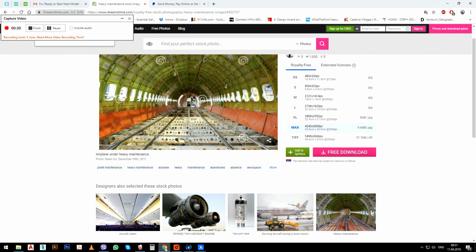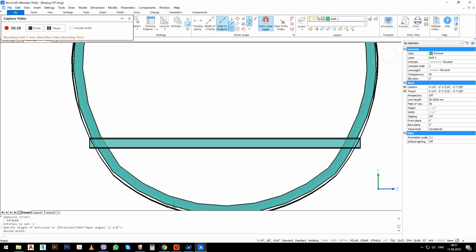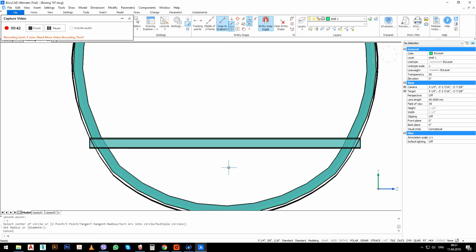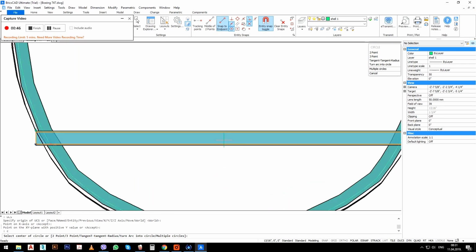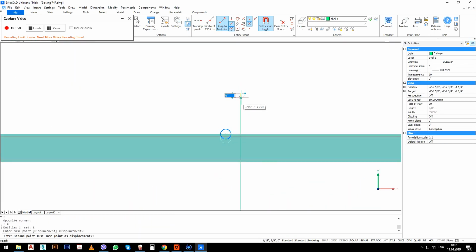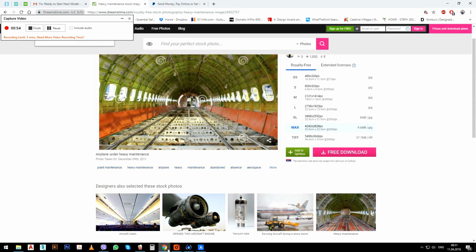And I'm going to do the circles now, circle holes on it. Starting from the middle. And after I make one side, I'm going to mirror it to the other side so I don't have to draw them again.